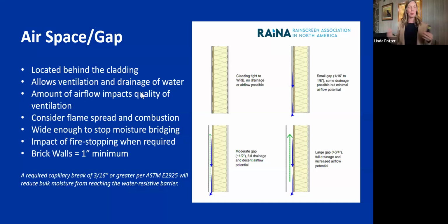But then also it's a practical reason of why you typically saw 2 inches of airspace. That's because as the mason contractor is taking a brick and installing it in the wall, their fingers have to fit back behind there. So is that 1-inch minimum that exists for an airspace in masonry valid for all Rainscreen assemblies, or are there other things we need to think about?